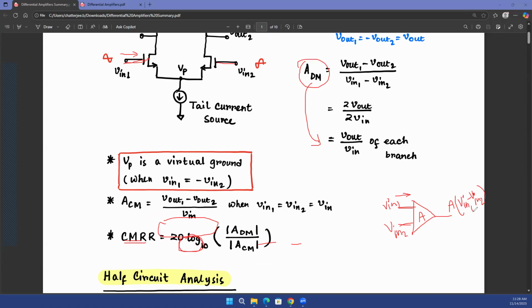Yes. So if you are building a MOSFET-based circuit, now if you build it using BJTs, we haven't yet talked about BJTs though, but I'll be talking about them toward the end. You have to apply a little bit of a different strategy to make sure that the input is still infinite impedance. But for a MOSFET, that concept is pretty easy. You just have the gate at the input. That means you apply some sort of a differential amplifier at the input side, and that will make the input impedance infinite ideally. And then the gain of the op amp we already know is A times V1 minus V2.